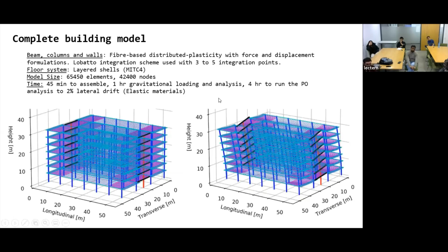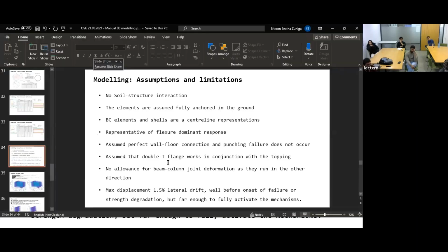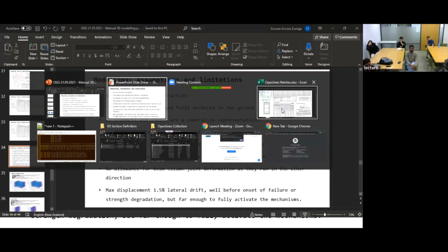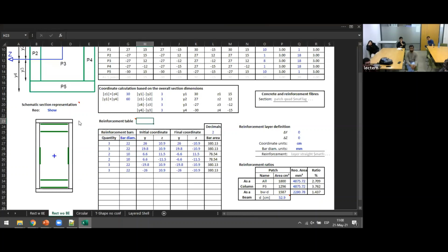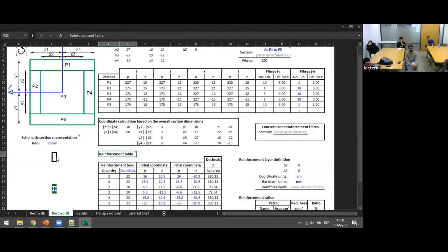I try to change the fiber sections, and I define them offset. So as you saw in here, I can provide offsets to the sections. So for example, I can provide an offset of 200 there, and the section will be defined with an offset with respect to the center.